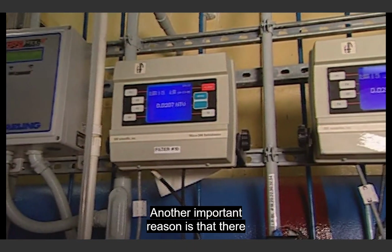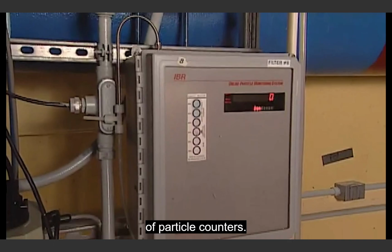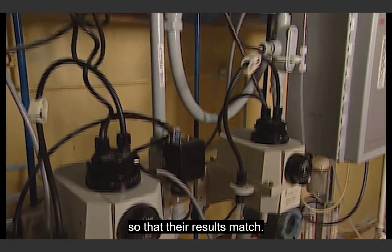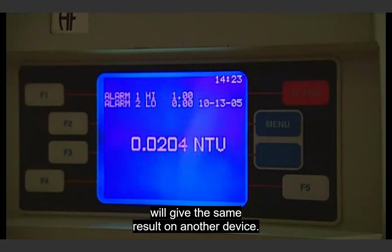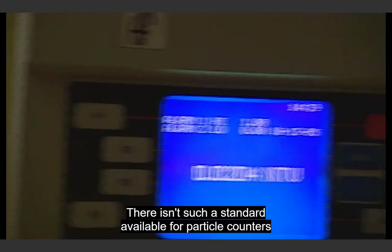Another important reason is that there isn't a universal standard for calibration of particle counters. There is an ASTM standard for turbidimeters. All turbidimeters can be calibrated so that their results match. A water sample measured on one device will give the same result on another device. There isn't such a standard available for particle counters at this time.